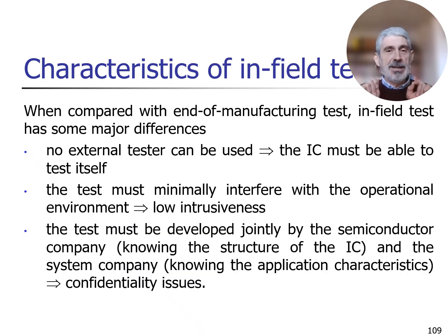The issue is that in-field test has some peculiar characteristics. First of all, we want to test the circuit while it is in the system, on the board, etc. So I cannot resort to a tester where I place the circuit, I apply stimuli, and I observe the answers. This cannot be done. So the only solution is that the circuit can test itself. So from the outside, I will ask the circuit to test itself, and the circuit should be able to do so for in-field test.